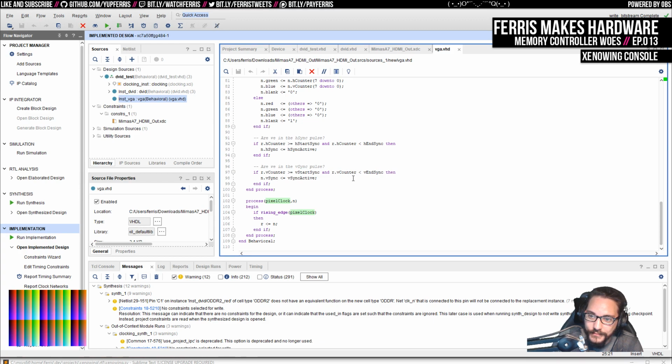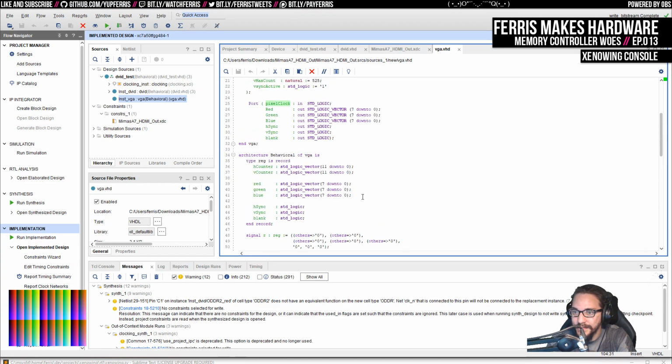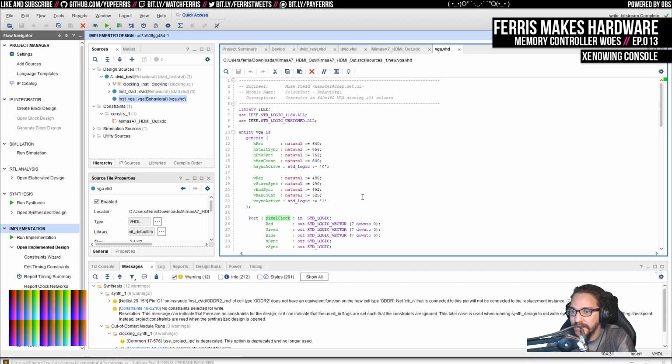And then having another part of my design that's based on this pixel clock that should be in phase with that. Yeah, I'm actually not sure. I need to think about that one a bit. It may even be that just to match this clock, we end up running the design at like 125 megahertz and do the TMDS within that domain. I'm really not sure. I need to think about that.